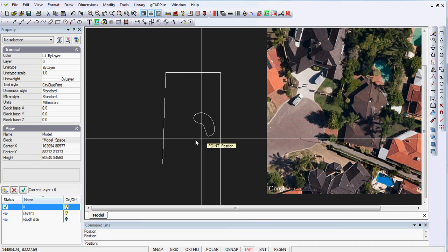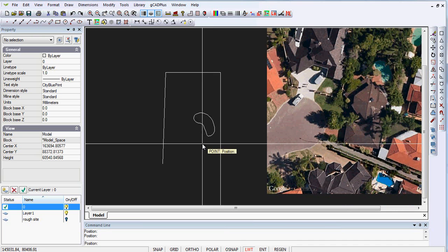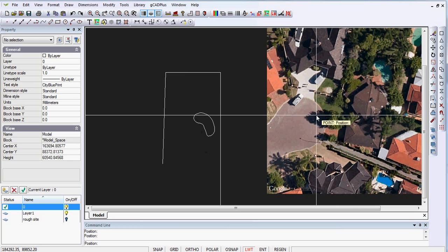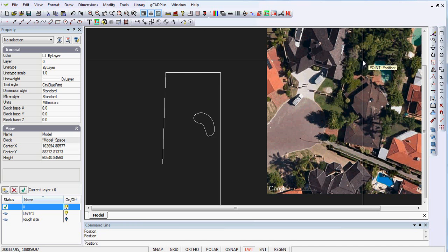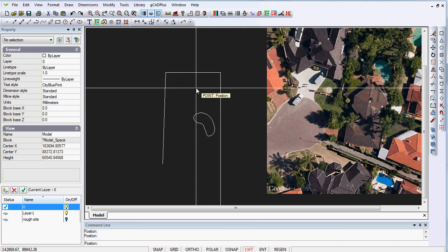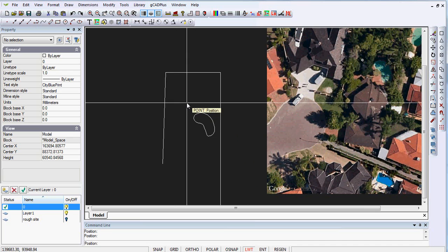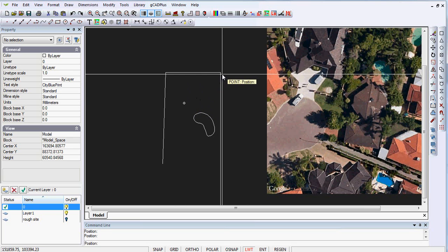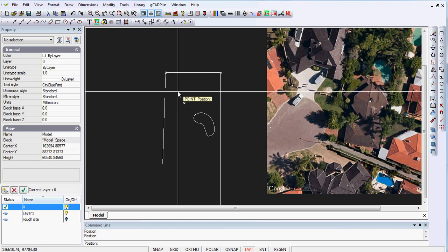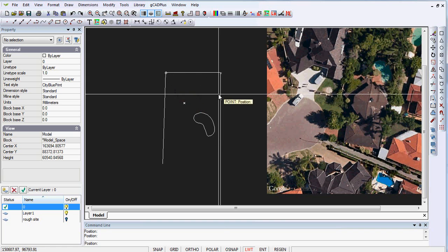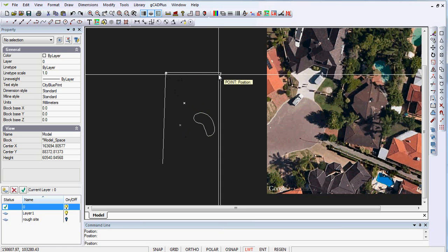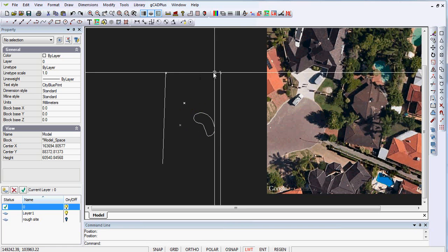and we've got a rough idea of the kidney-shaped pool location. There's clearly a whole lot of paving within here, and we would now want to locate that paving accurately. So let's, for the sake of argument, say the paving ends at some point there. You would then be able to measure from the end of that paving across to this corner, and from the end of that paving there across to that corner, and if you had another set out point, say somewhere here, measure there to there, you could use the resultant triangles to accurately place the back boundary.